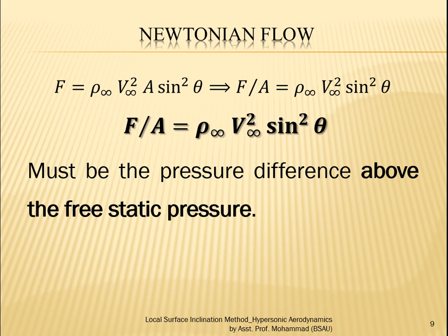So the fluid as a whole is not moving, the whole bulk is not moving, but the particles are moving. This movement of the particles gives the static pressure. Whatever Newton has calculated is above this static pressure, so he is going the dynamic way. The force per unit area calculated from Newton's sine squared law is something above the static pressure.